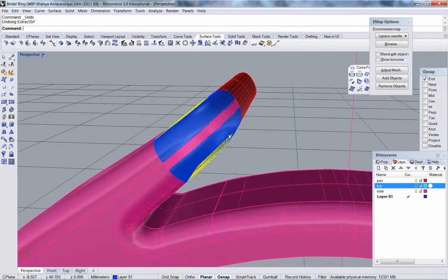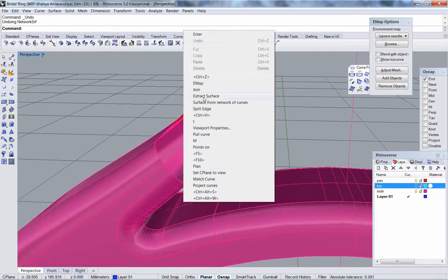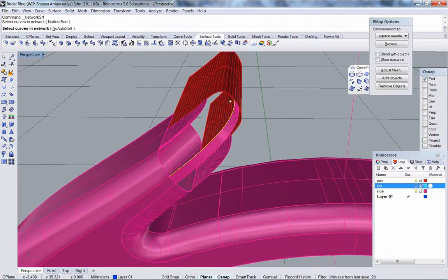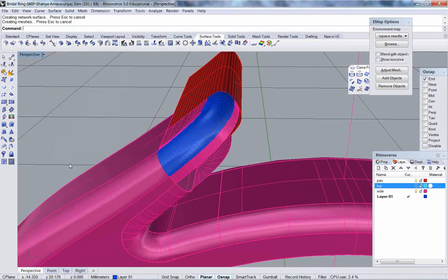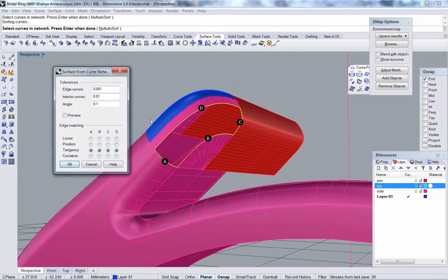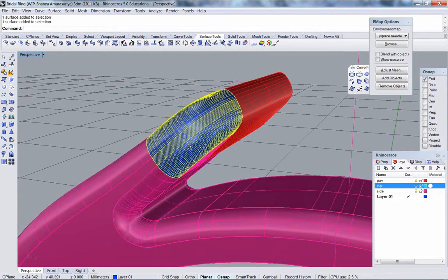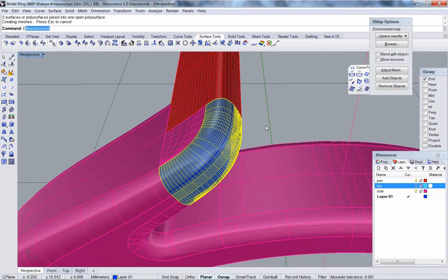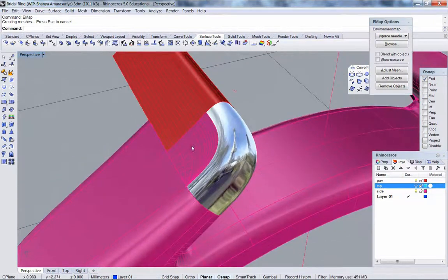So what I'm going to do is back up. And I'm going to set this to curvature coming off of here, which will give it even more smoothness. But I may not be able to do a whole lot smoother than that. B edge. We want to change from tangency to curvature. D edge. We want to change from tangency to curvature. That may have helped. Yeah, that's better. Okay.